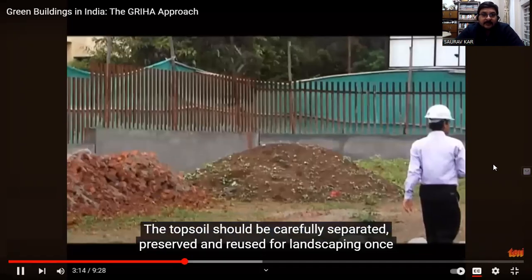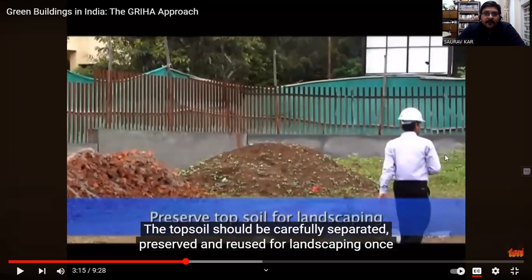See here, the topsoil, when we go for a civil engineer, we go for soil work excavation, soil work removal. When you come to second year, we learn the estimation and costing of the soil removal. The topsoil, what happens? It's very lucrative. It's very rich in humus, fertile, and very rich in plants. When you're removing the topsoil, a site engineer should be there to take care of that. The topsoil is dumped in a separate area. When the construction is completed, again the topsoil will be used for gardening and landscaping.